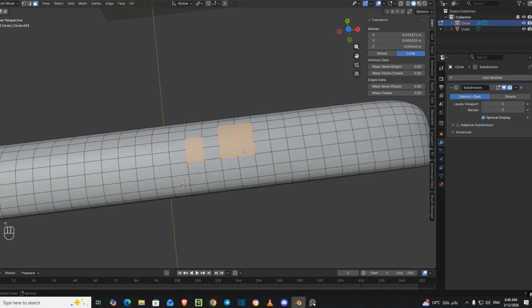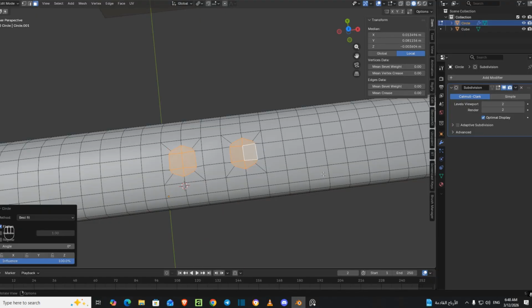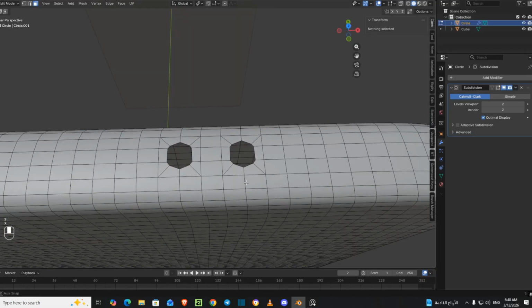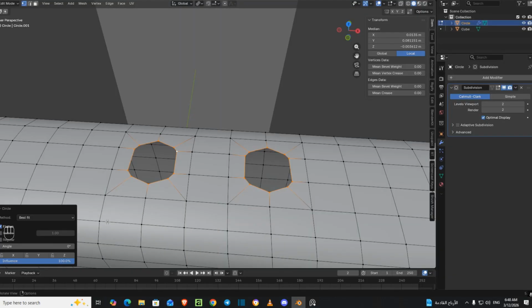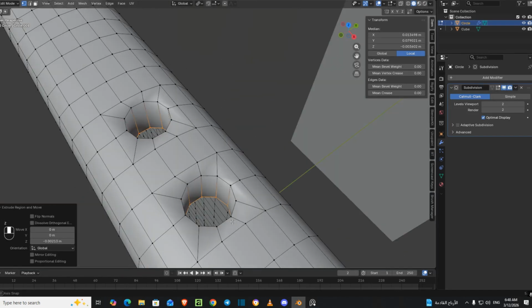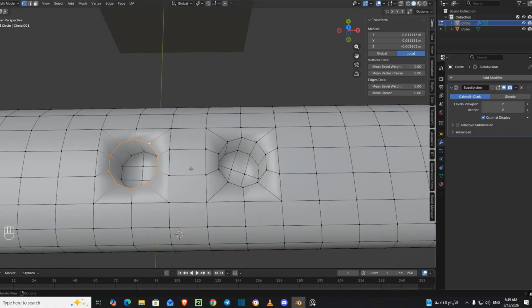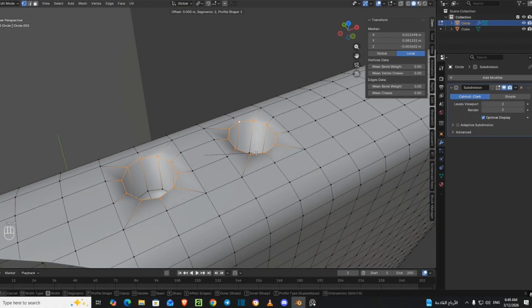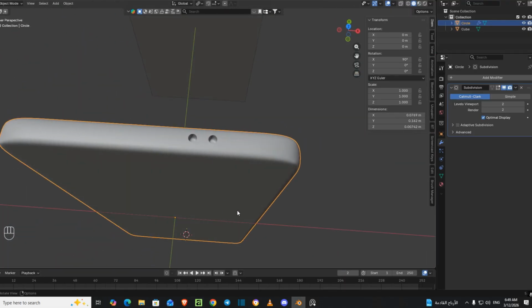Let's select all these faces, all these faces and all these faces. Inset, loop tools, circle, scale down a little, delete faces, and select these parts, circle, regular, extrude along the z-axis, select each one, grid fill, this one as well, grid fill, select this, and this, Control B, add a bevel, 2 in the shape of 1. Okay, that's looking good now.